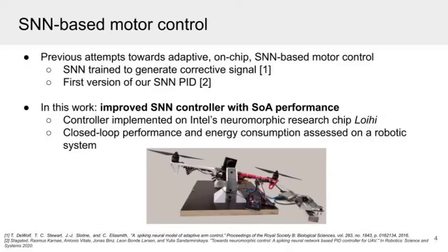Attempts have already been made towards adaptive on-chip SNN-based motor control, for instance in this work done at University of Waterloo, where an SNN was used to control a robotic arm. Earlier this year, we showed our first version of an SNN-based PID controller. Now we have improved the integration precision as well as the closed-loop response time. Furthermore, we have measured the power consumption of the Loihi chip in progress.